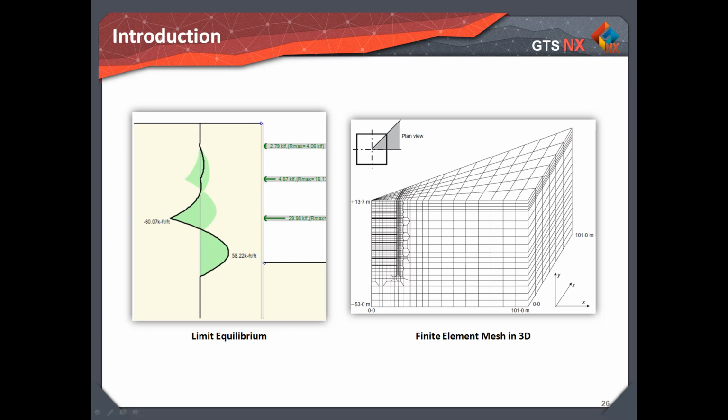Fundamentally, the limit equilibrium design method for the analysis of embedded retaining structures assumes the wall to be rigid and the soil to have rigid, perfectly plastic behavior. The earth pressure derives from the interaction, depending on the expected movements of the wall and the mobilization of active and passive lateral earth pressure triggered by such movement.